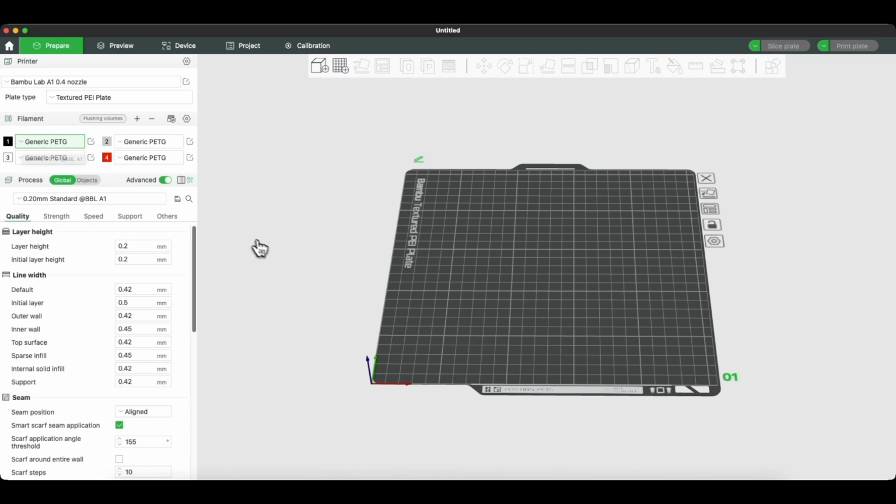Now we select the material we are using. I currently have PLA in red color mounted in this AMS slot, so I will leave this color, but I changed the type of material from PETG to PLA. Next, we select the print parameters related to the technical aspect of this print. Here we specify filament parameters mainly related to flow or temperature of the filament, and here we define parameters such as layer height, number of layers, or percentage of infill.